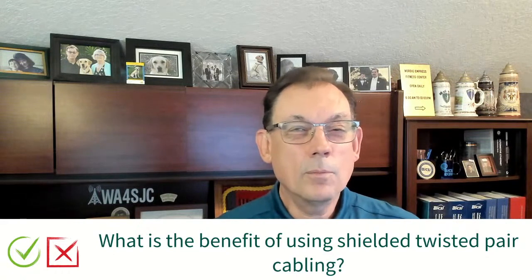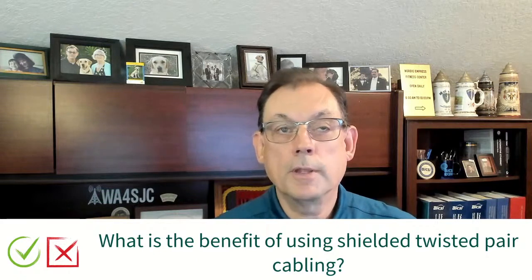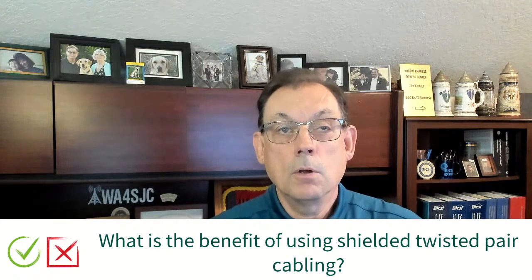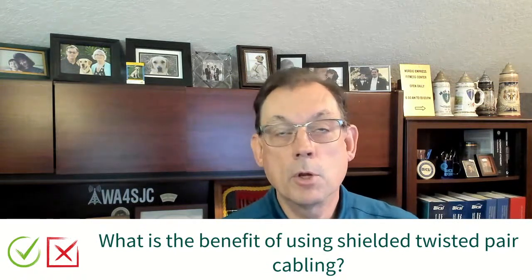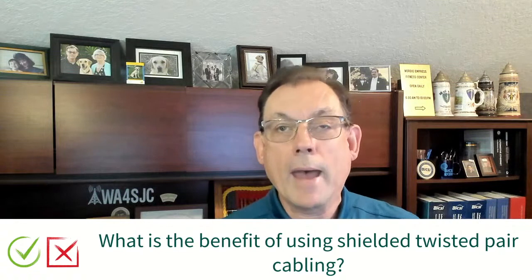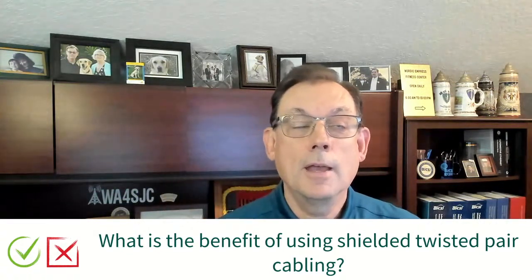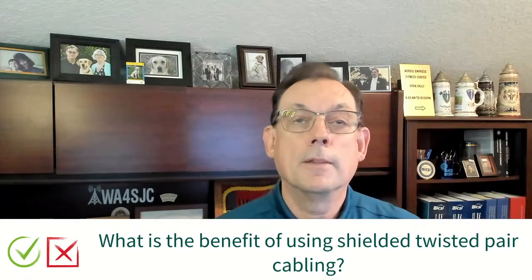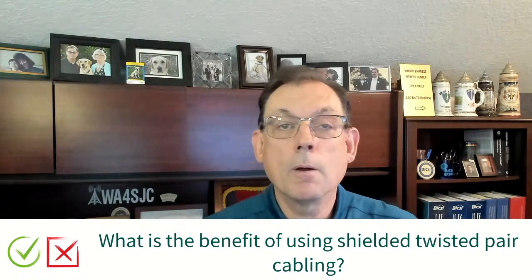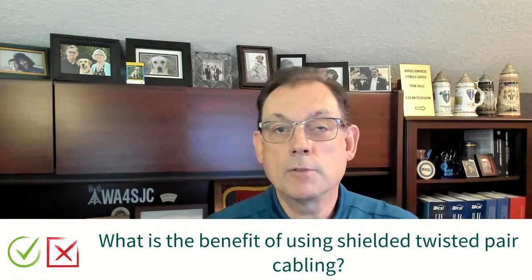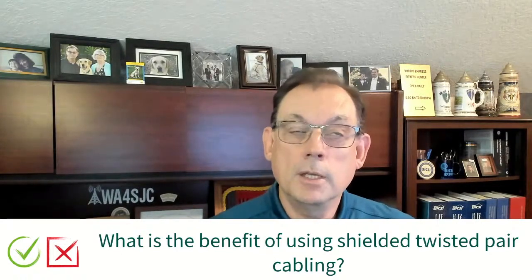You might think, what are we talking about with noise getting out of the cable? There's something called alien crosstalk, which means you're getting signal from one cable bleeding over into another cable. We're all familiar with crosstalk between pairs. If we go way back to the olden days, using a landline telephone and hearing somebody else's conversation, that's crosstalk in its very basic form. That conversation bleeding over from another pair is why it's called crosstalk: you could hear the talk from another line bleeding into your line.